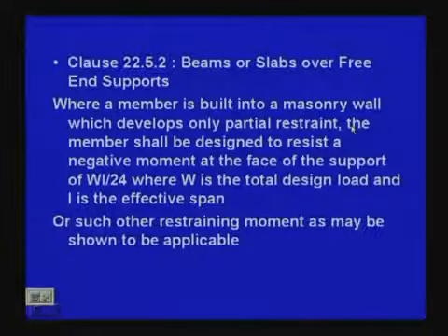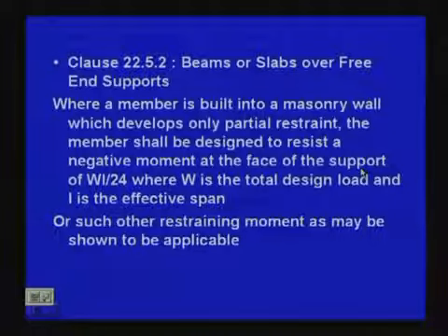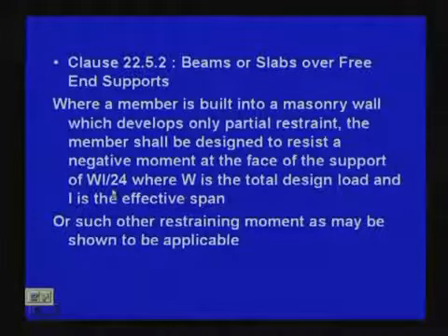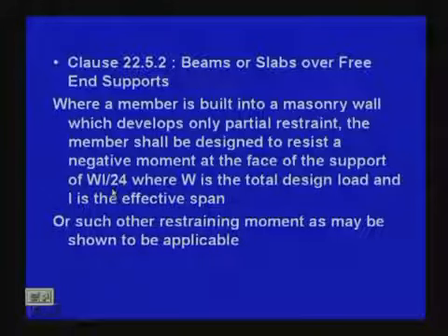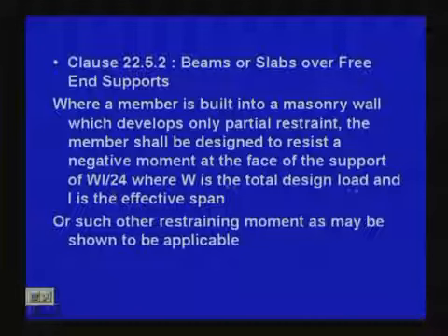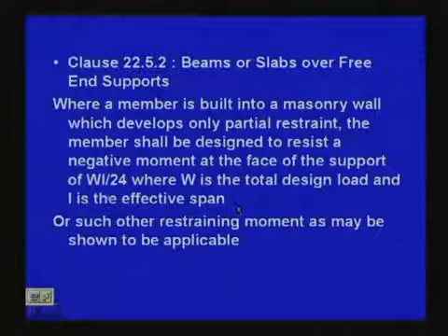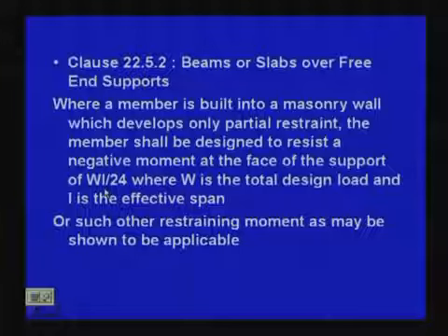The member shall be designed to resist a negative moment at the face of the support of WL/24. Instead of having WL/12, W is the total load in this case, and L is the effective span. So, WL/24, that means we are taking half of that.